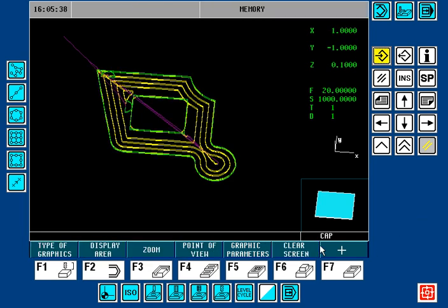Very nice. Here you can see that we machined not only around the inside profile, but we also machined around the island and applied finish passes to both of those features. Here is the Boolean add, where we added this portion by an overlapping shape, and here is the Boolean subtract, where we subtracted that portion by making the start point of the circle inside.